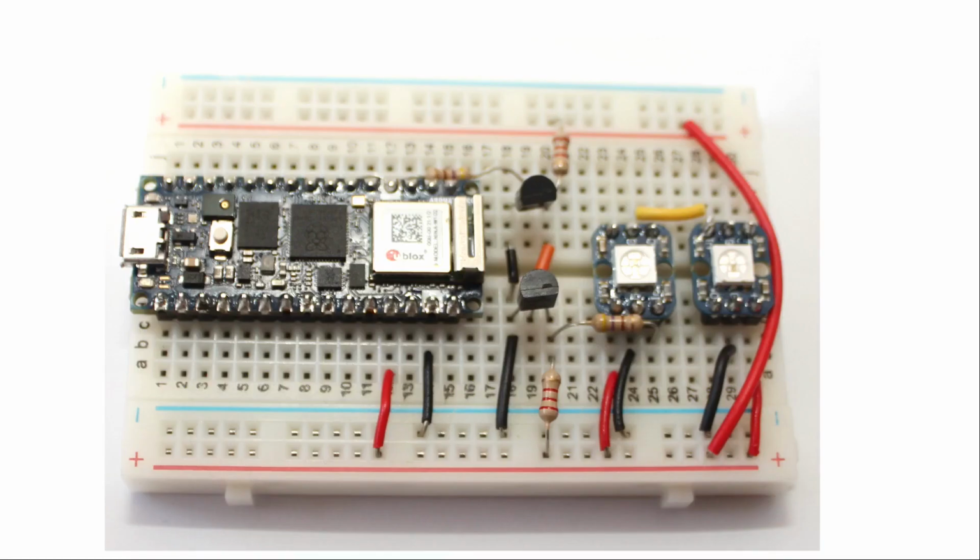This circuit is still on a breadboard in the prototyping stage. Instead of using the two breadboard LEDs shown here, I've now connected this to a 1 meter long strip using WS2812B RGB pixels. And this allows me to test the proper light sequences.